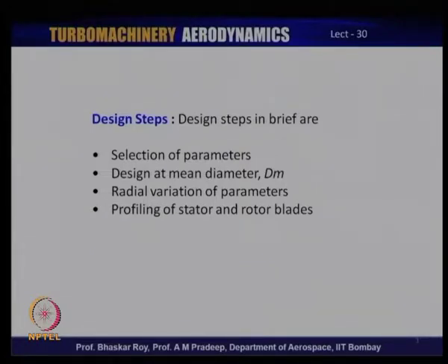So, design at mean diameter is an important step, and it often is not a very quick method, even though we will go through a very quick round of steps, but quite often it does take a long time before the mean diameter design of all the stages of a multi-stage turbine is completed and appropriately matched with the axial flow compressors, which they are supposed to power. And then of course, you take the radial variation of all the parameters, the flow parameters and the geometrical parameters of the blade.